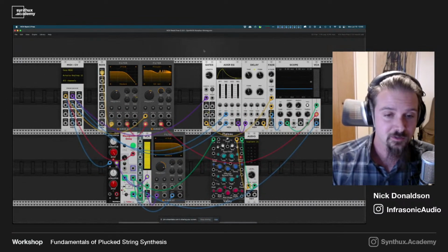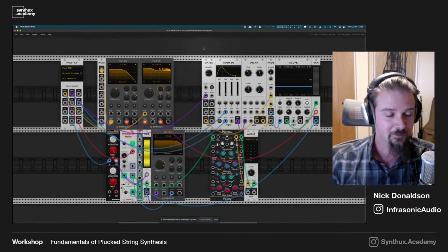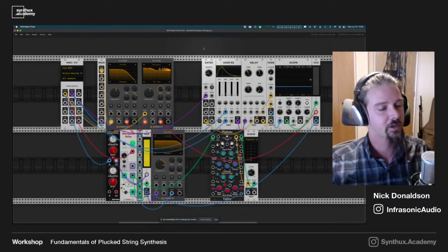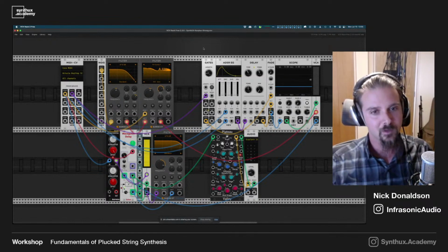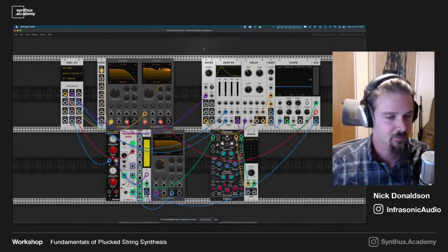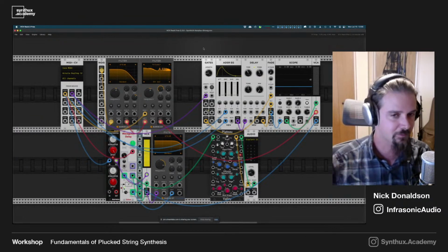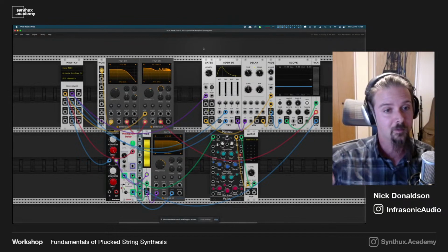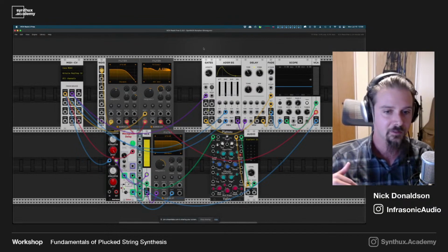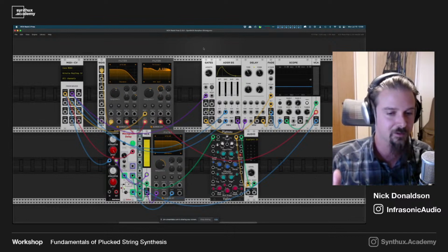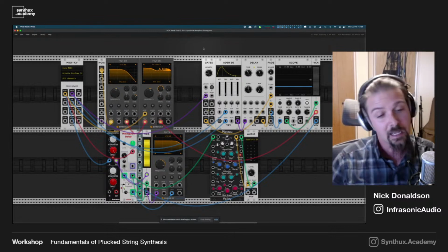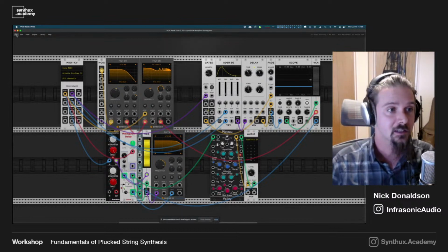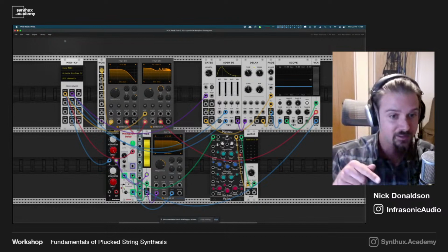To think about this from a physical world analogy, the delay line and the feedback filter in the delay line, you can think about that as the resonator piece. So once we have some sound in our system, once we've excited it with some energy, how is it responding over time? We're damping the high frequencies. The harmonics of whatever period of delay we have are building up, because I didn't mention this earlier, but the reason that happens is because of constructive interference. So, we're adding it back on itself.